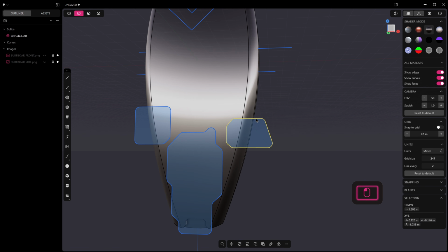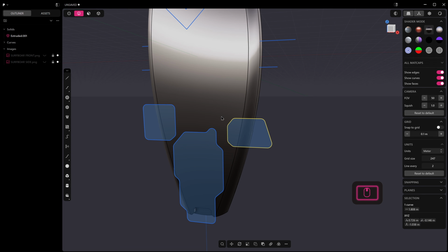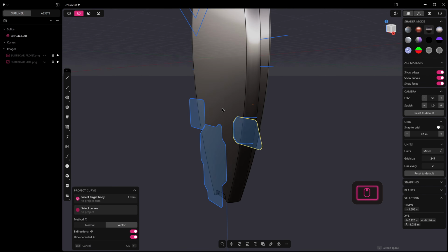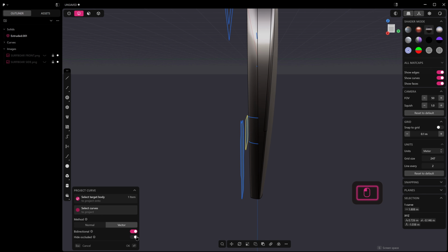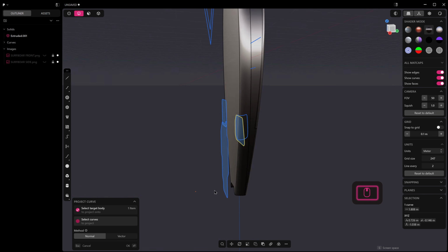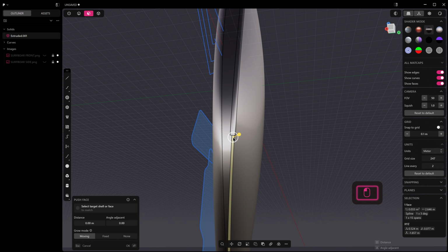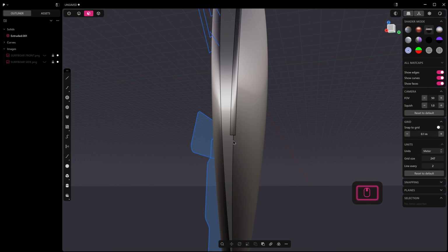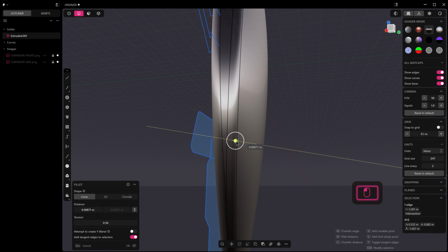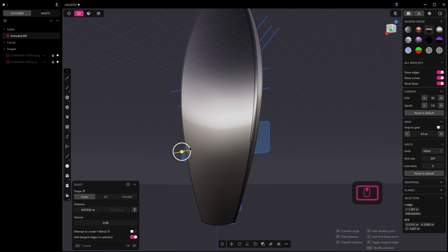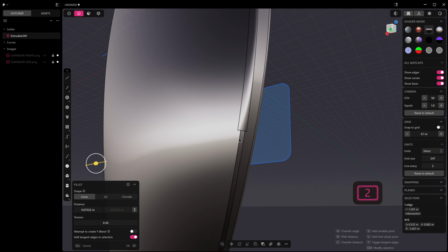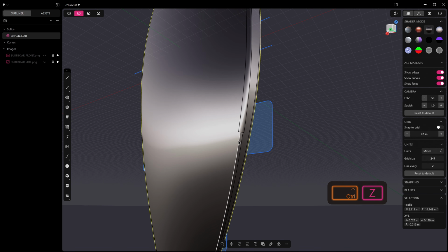So now what we can do is select this and hit I and then this object. And then we want to turn hide occluded off and go to normal. Or actually, that whole thing that we just did probably ruined that. So let's just fix those fillets up. If you went through that whole process, just go back and start again, which I'm going to do.